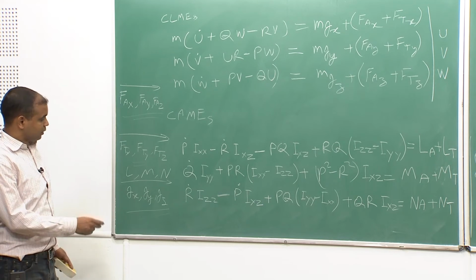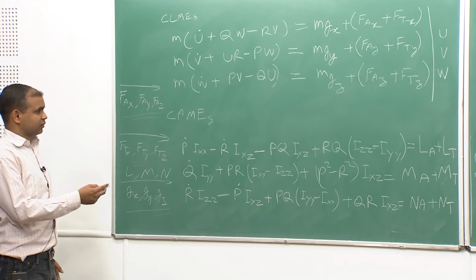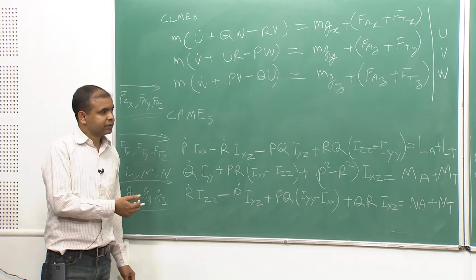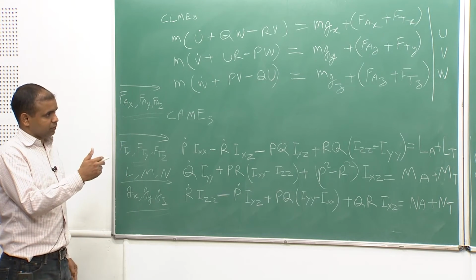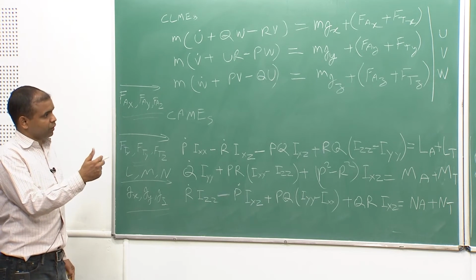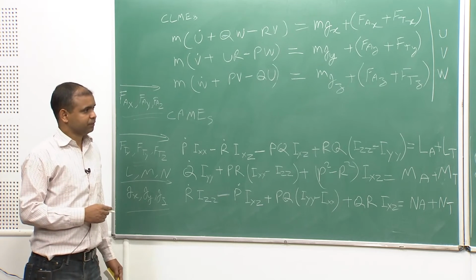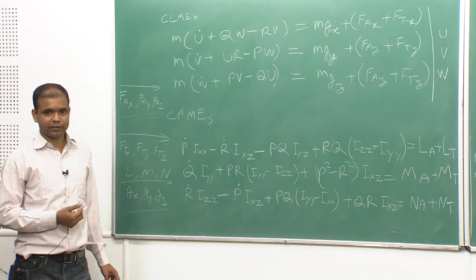If you keep iterating, the new values work as the initial condition for the next iteration, and you will get the values after 2 delta t, and similarly if you keep iterating, you will get a continuous path of the aircraft, that is our trajectory.